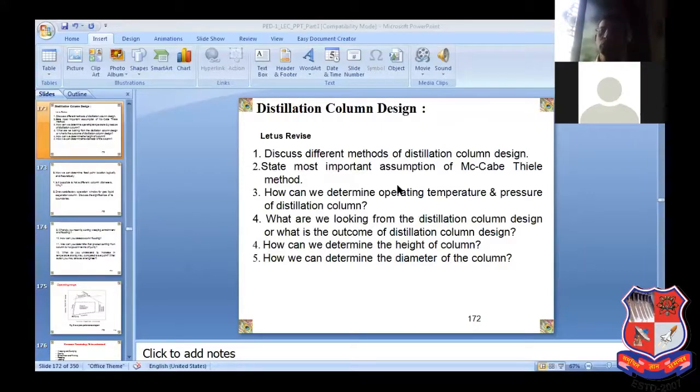So how can we select the pressure? To some extent we have learned this in the packed column. Here the operation is not decided only based on the feasibility of the distillation. Apart from the distillation, we need to check other possibilities. Let me give an example.